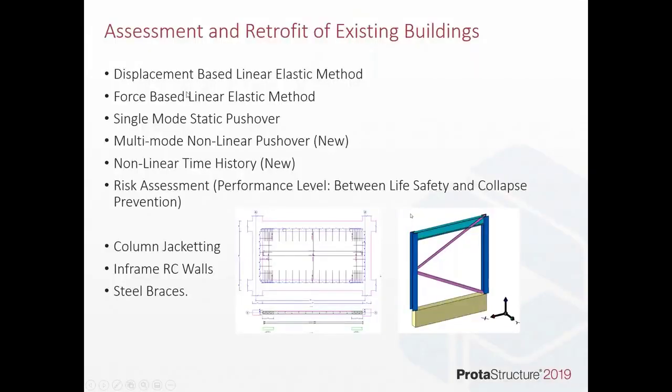We can look at base isolation. Another thing that I haven't really touched on today is the assessment and retrofit of existing buildings. This is really looking at performance-based design of both existing and new buildings, and we have different approaches for this. You could be doing displacement-based or force-based, single mode, multimodal, or non-linear. Time history and pushover analysis can be performed.